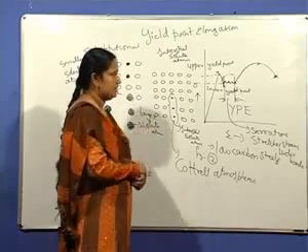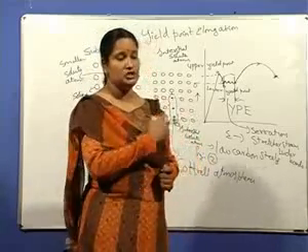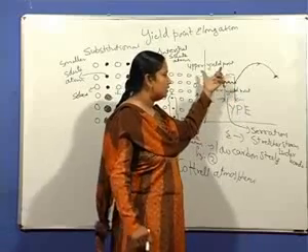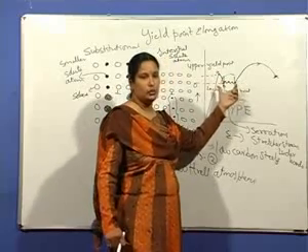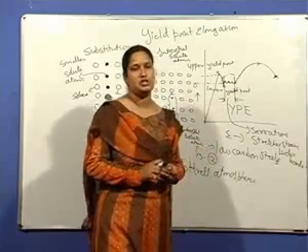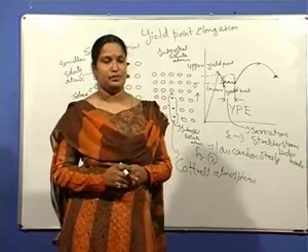There are certain disadvantages of the formation of this lower yield and this serrated portion of the curve. These are the structure strains, which are also known as Luder bands, that form during the plastic deformation of low carbon steel sheet materials.